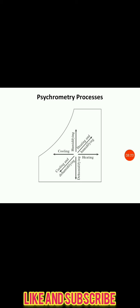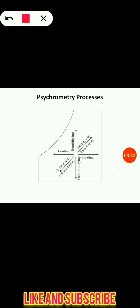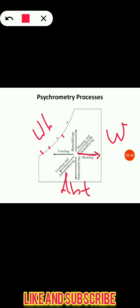Then there are different air conditioning processes that are generally carried out in an air conditioner, like sensible heating, and generally that is plotted on the psychrometric chart. This is the psychrometric chart, this is the omega, then this is the dry bulb temperature line, the horizontal one. Then here we have different wet bulb temperature lines, along with dew point temperature lines, and then the specific enthalpy lines. So these are all the psychrometric properties that we can plot on the psychrometric chart.